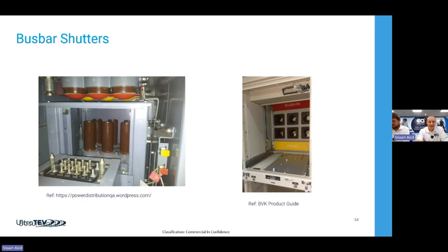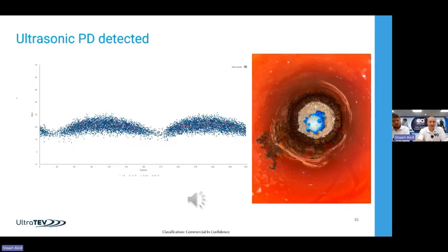So I've got a couple of examples and a picture on the next slide. This was one that we detected in service. It's a switchgear lineup, VMX panel, and all the other ones were running, and this one had its breaker racked down. But literally just put your microphone into that little area and we could hear it clear as day. And it's actually on the circuit side, and you can listen to that sample as well. This thing is relatively loud.